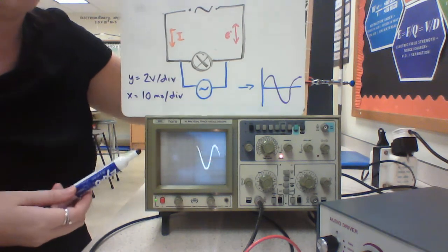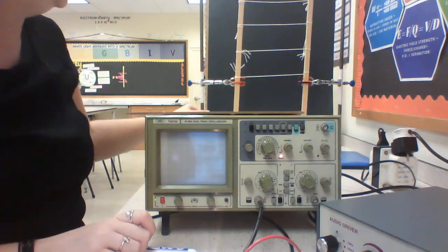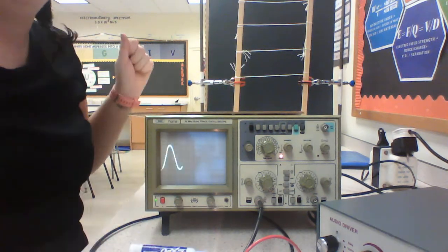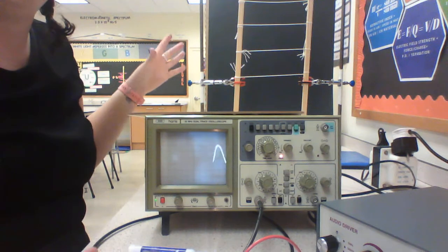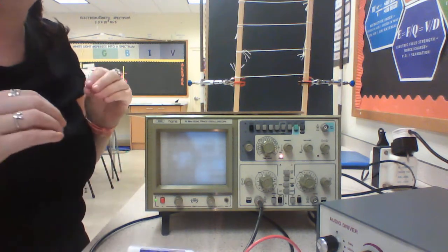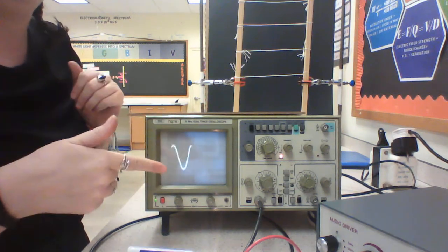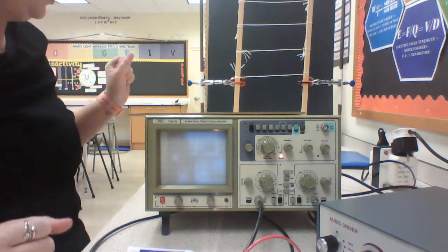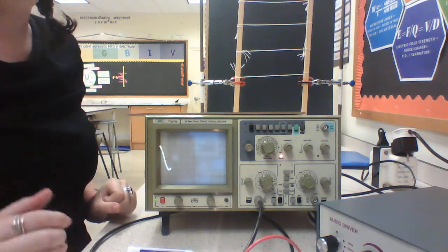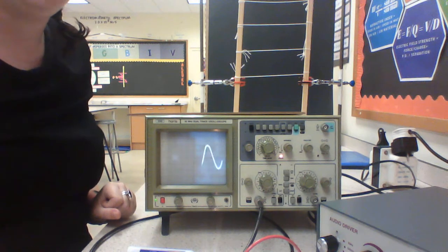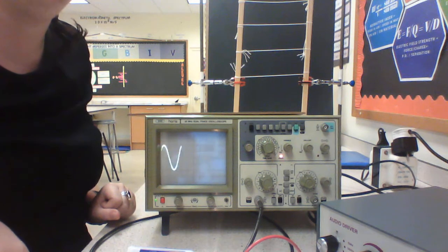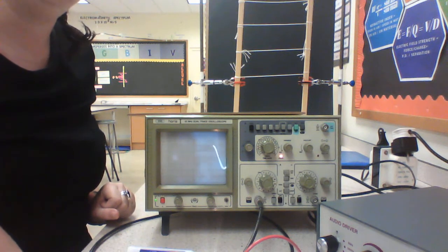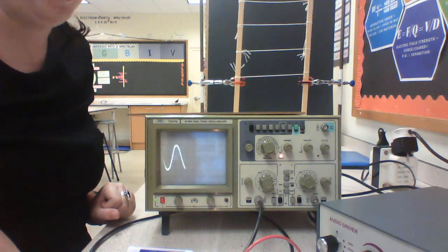The way that we get the electrons to do this is to use an AC generator. I just wanted to look at the AC generator and where the coils are compared to when you get your max and your zeros on your oscilloscope, because I know it can be confusing. It's remembering that Faraday's law of induction is the rate of change of magnetic flux is the size of induced EMF.